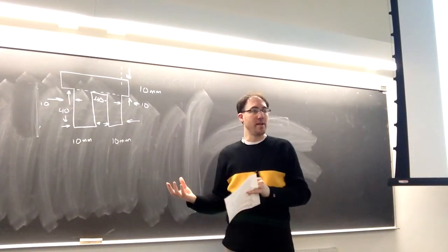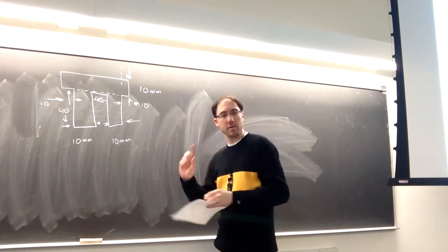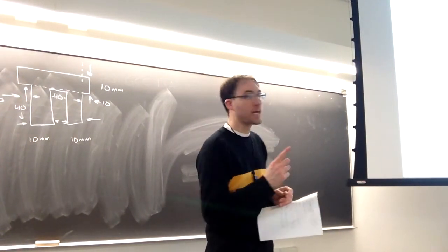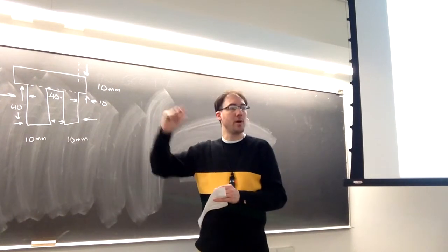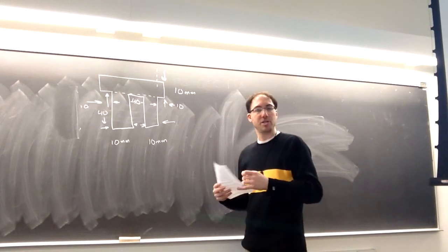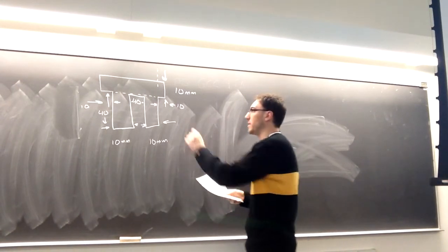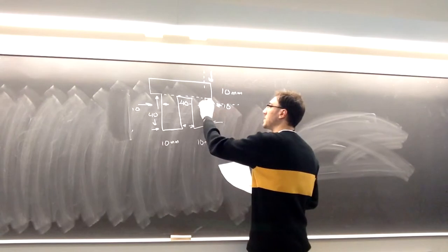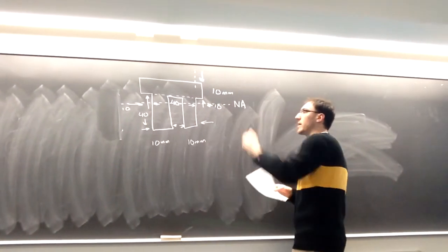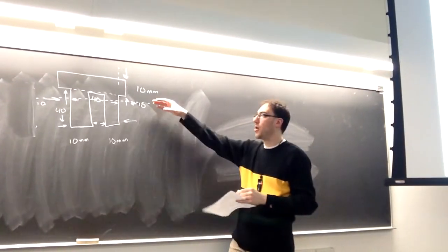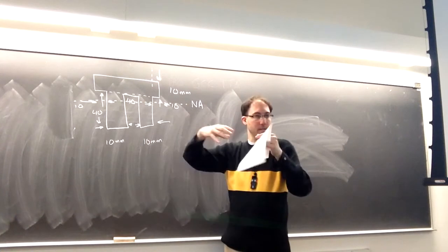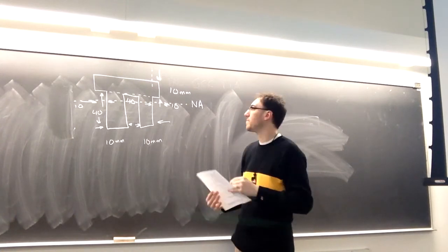As we saw in 211, if we want to find the moment of inertia, well, first thing we need to know is where's the neutral axis located? Because to find y, we need to know our distance from that neutral axis. And again, the neutral axis coincides with the centroid. So somewhere along this is the centroid of the shape, and that's going to be the neutral axis. That is where, when it bends, this plane does not contract, it does not expand.